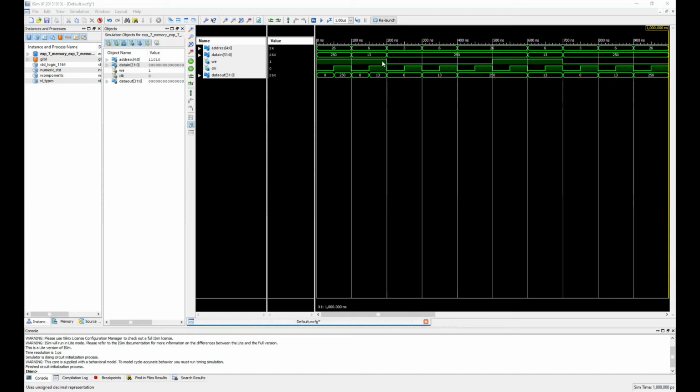Then we have the enable. After that, the enable has gone to 0. And in that case, we have specified the address as 3. In that case, the device is in reading mode. So far, it was in writing mode. I mean, it was storing values, but now since the enable port is 0 and there is nothing to be stored, rather it's going to read the value.